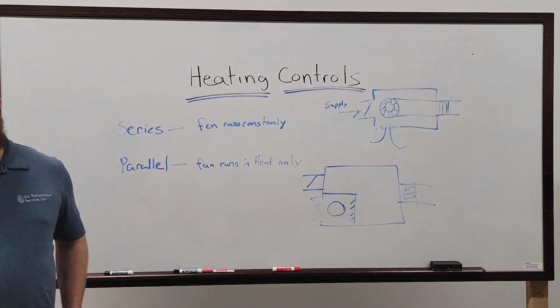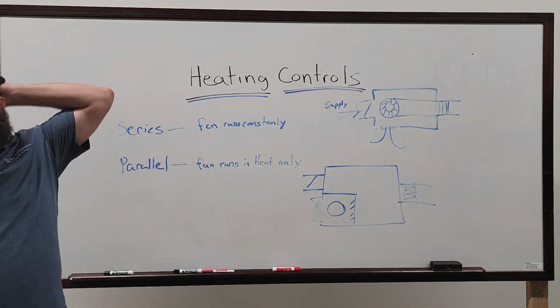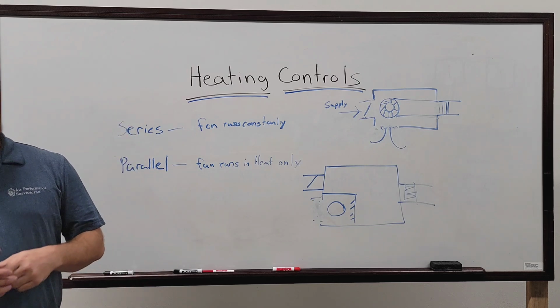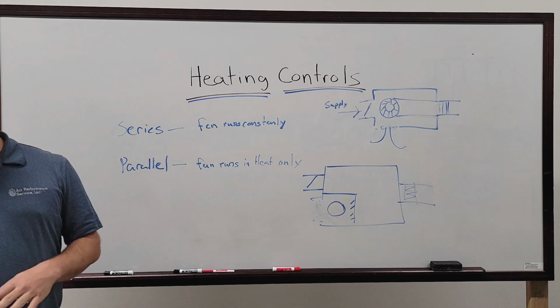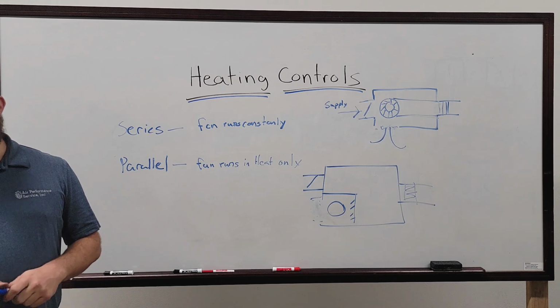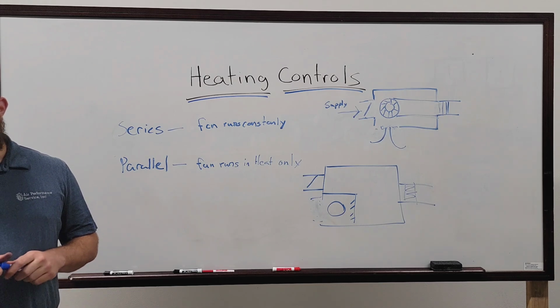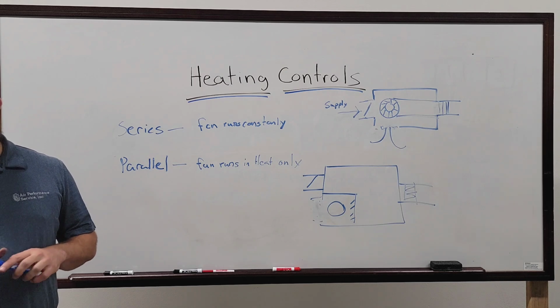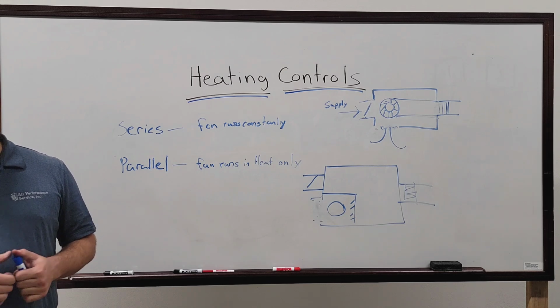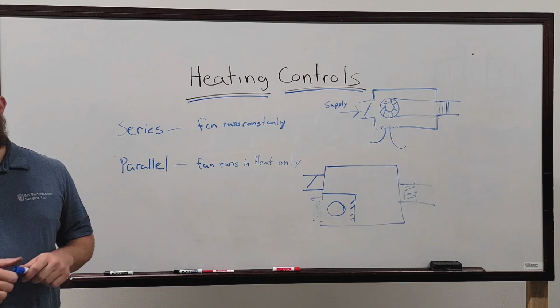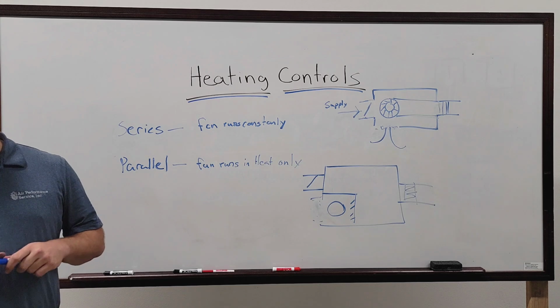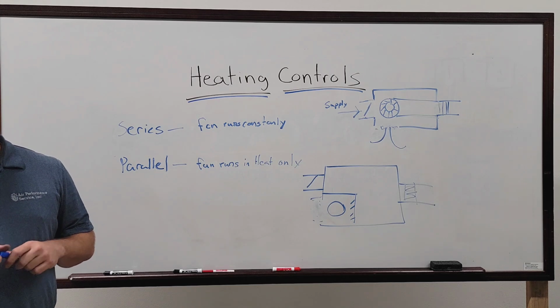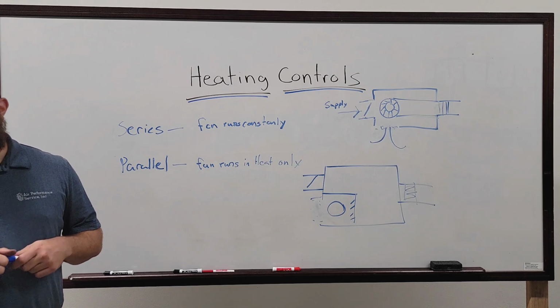Well, I mean, because a lot of the buildings that we've done were pneumatic, and there are ways to do modulating outputs with pneumatics, but it is complicated, you know? Yeah, you have to have an E to P, or a P to E, a pneumatic to electronic transducer. So it takes your 9 to 13 and converts it to a 0 to 10 or a 4 to 20, and will then drive a heater that way.